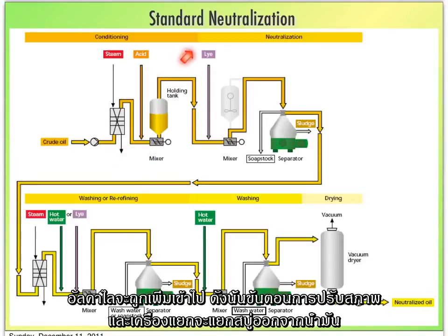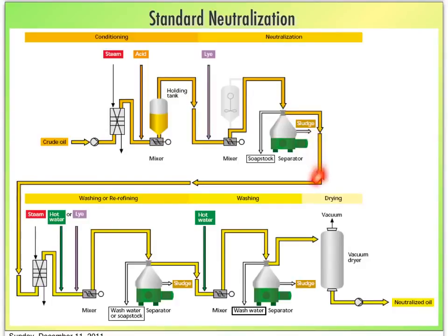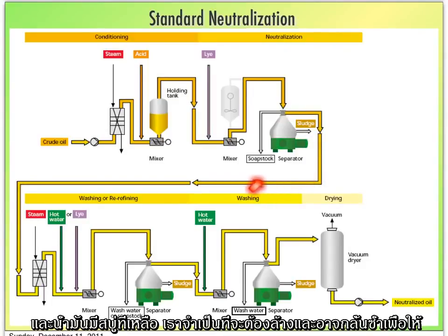Then the alkali will be added. So this is the neutralization step here, and the separator will separate the soap stock from the oil, and the oil might contain some residual soap stock, so it will require probably a few steps of washing and maybe even refining.